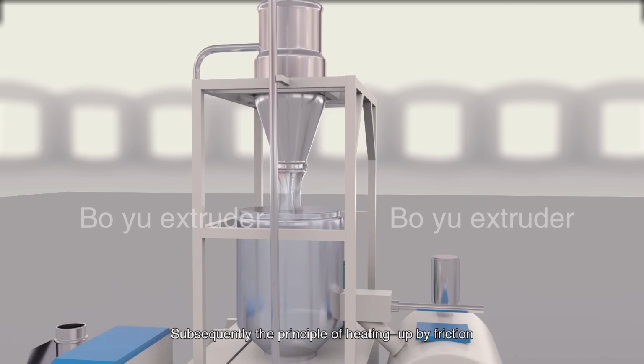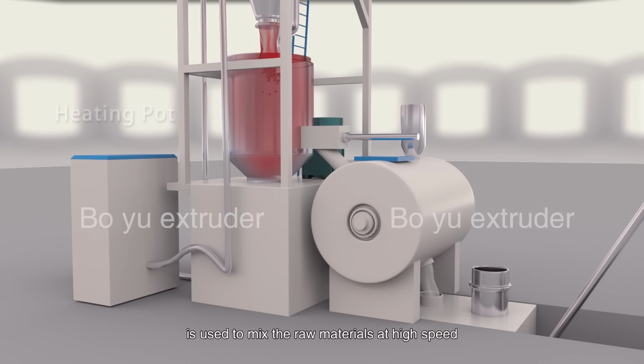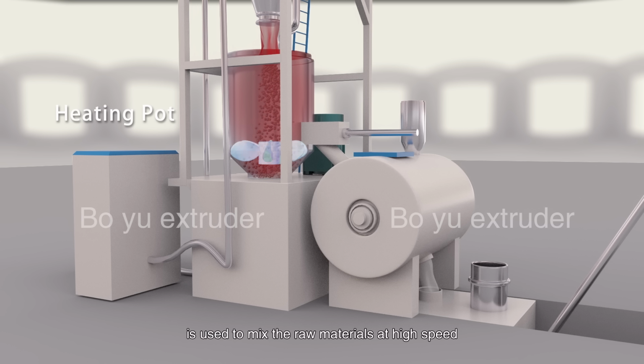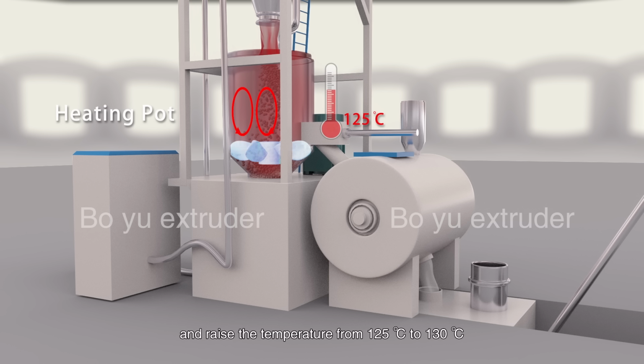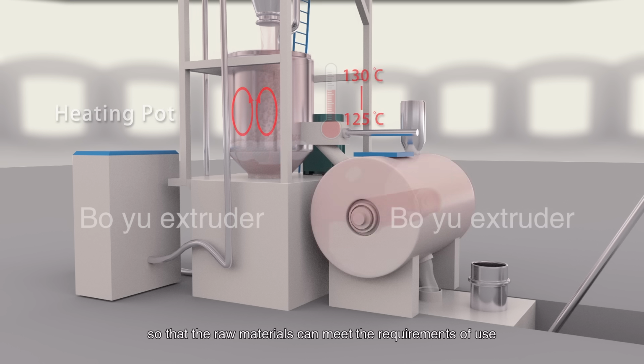Subsequently, the principle of heating up by friction is used to mix the raw materials at high speed and raise the temperature from 125 degrees centigrade to 160 degrees centigrade, which will make the processing aids melt and the water vapor be removed from the raw materials, so that the raw materials can meet the requirements of use.